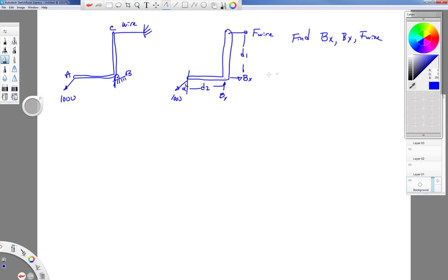All right. If we want the average shearing stress in the pin, then we know it's the shear force in the pin, I'm using the symbol V for my shear force, divided by the total area in shear. And we know now about single shear and double shear, so that area could change depending on what case that is.